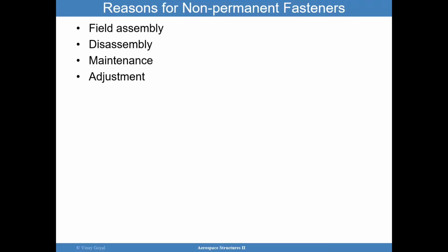Well, if you were to use a bonded joint or a weld design, you will not be able to disassemble as easily as with a bolted joint. And as a consequence, a bolted joint does provide some advantages over these other more permanent joint designs.